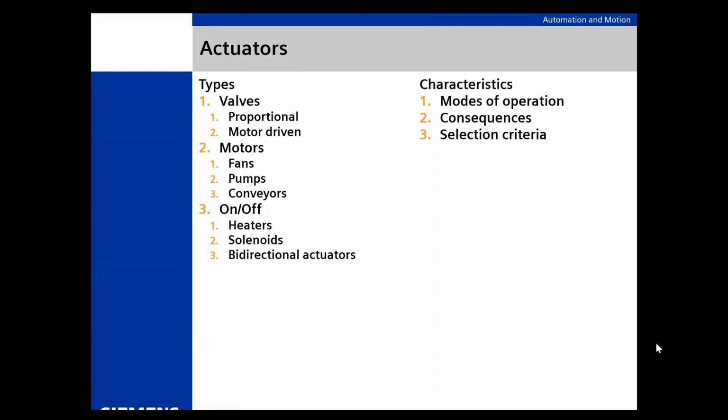It's repositioning a valve. It's turning something on and off, or it's modulating something. So the controller is telling something to do something and getting the feedback from some instrument or sensor to let it know, yes, I'm on set point, quit doing that, or I need to open that valve, or I need to speed the fan up or turn the fan on, or whatever it is I have to do. That's what we're all talking about here.